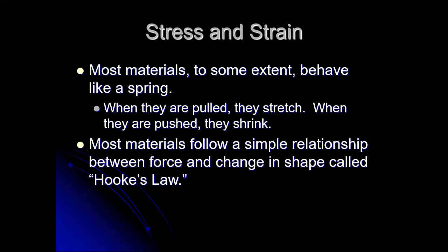And with most materials, there is a relatively simple relationship. As long as you don't push it too hard or pull it too hard, there's a relatively simple relationship between the force and deformation. We call that Hooke's law. Those of you that have studied a little bit of physics before may have come across Hooke's law. Hooke's law was your spring law.